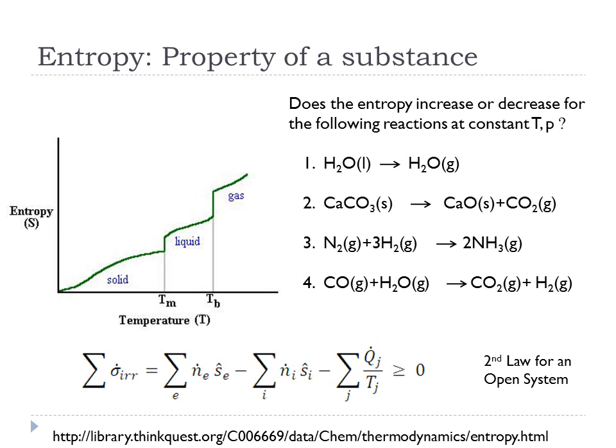So once again, there will be a certain temperature at which we can remove CO2 from calcium carbonate and not generate any entropy. But it would take place really, really slowly, because there would be no driving force. So to have this take place in a reasonable amount of time, we're going to end up having to use heat of higher quality than what would be the minimum set by the second law. But you can't go lower than that minimum, or else you won't get the CO2 to come off.